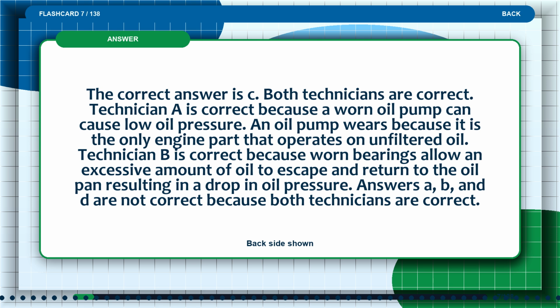Technician B is correct because worn bearings allow an excessive amount of oil to escape and return to the oil pan, resulting in a drop in oil pressure. Answers A, B, and D are not correct because both technicians are correct.